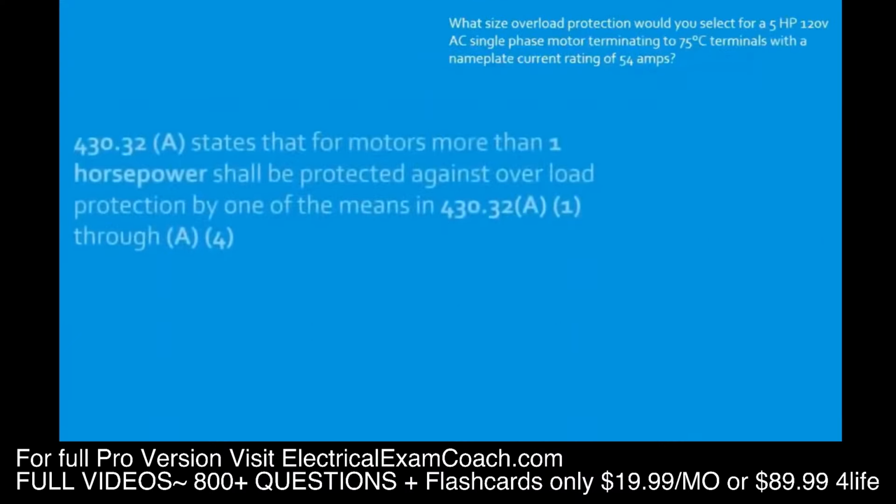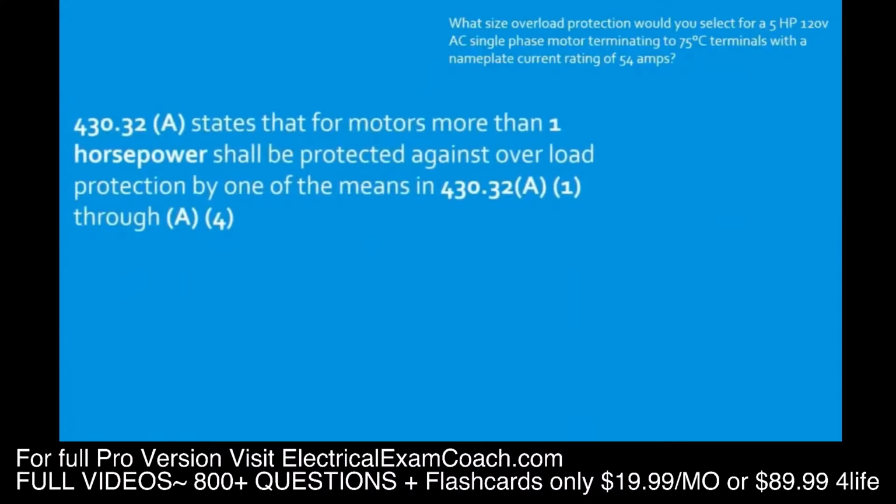All right, when we get to 430.32(A), it states that motors that are more than 1 horsepower shall be protected against overload by one of the following means, and it lists A1 through A4. We're only going to be dealing with part A1. It says separate overload device. A separate overload device that is responsive to motor current. This device shall be selected to trip at no more than the following settings.